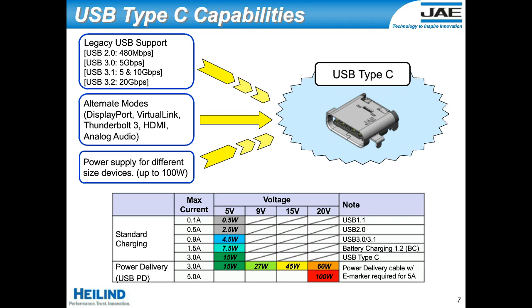Even with the USB Type-C connector, the power level will return to default USB power if higher power is not necessary for that specific application, or if it is determined that one of the devices that's connected is a legacy port. Default USB would mean the 1.5 amp or less current supply.